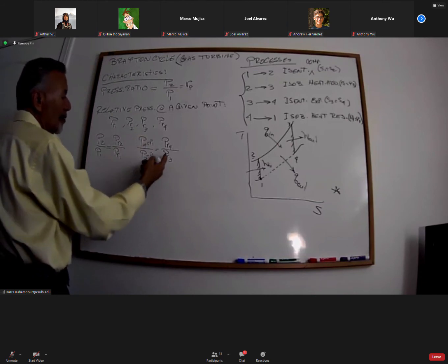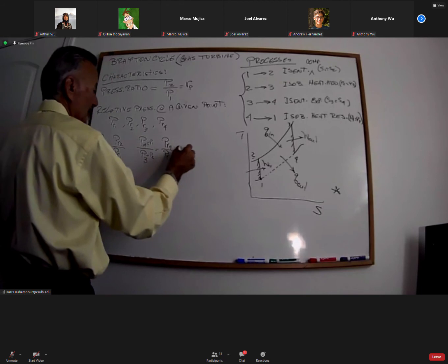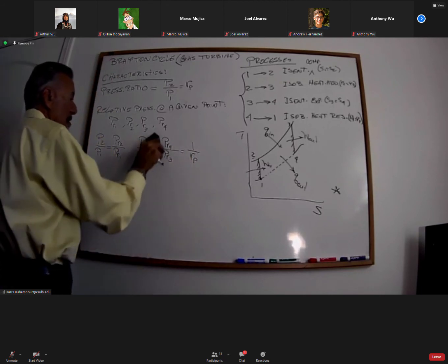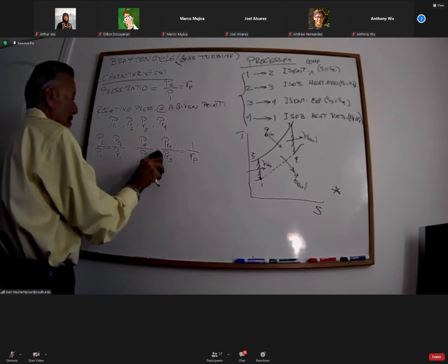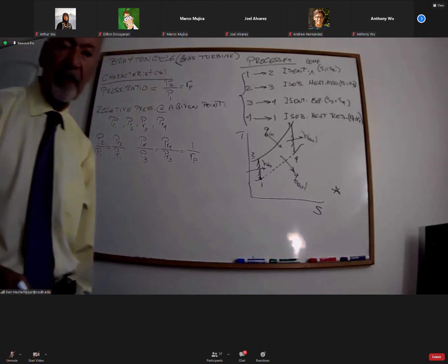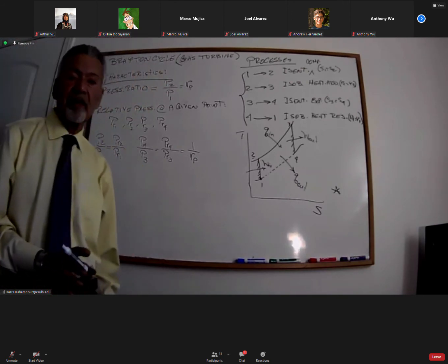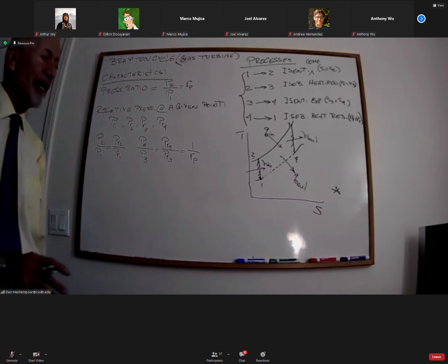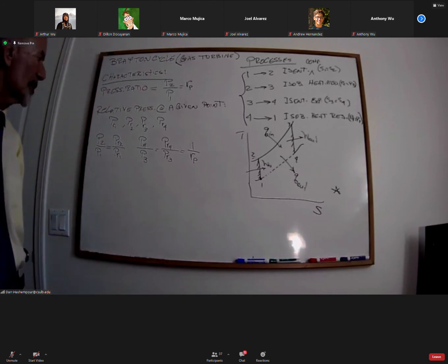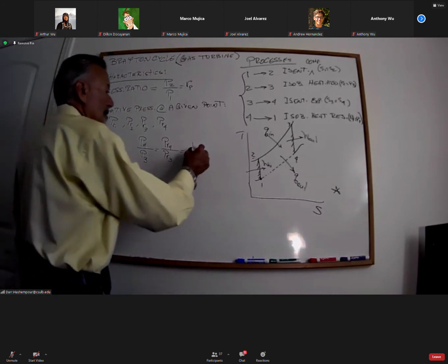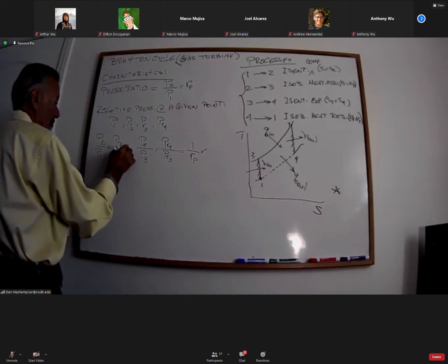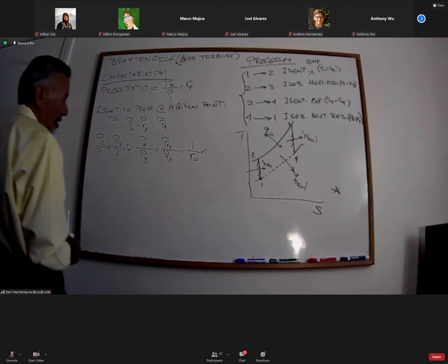That means PR4 over PR3 is the reverse of R of P. In an Otto cycle, we had the reverse. However, the diesel cycle was different. We found out there's a cutoff ratio over R of P. We just solved 3 problems. So remember that, and of course, this is R of P, and this side is 1 over R of P.